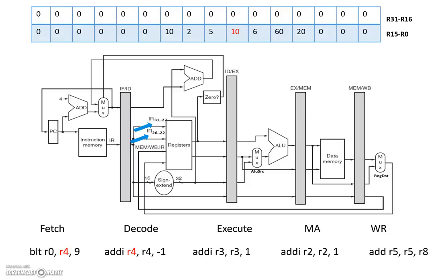Now again at this particular clock edge, fetch and decode will have a common register R4 and stalling must be done. This will happen in all the latter stages, and execution of the write back instruction will increment or decrement the value at the register file.